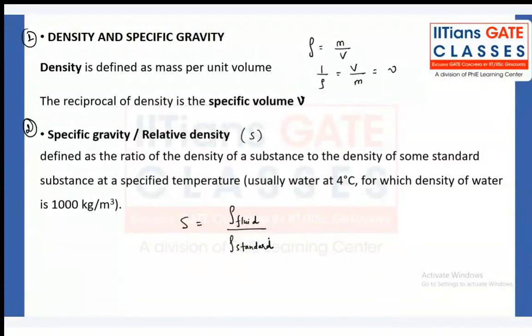Now, which fluid is to be considered as the standard fluid? In case of liquid, we generally consider the density of water at 4 degrees centigrade. In case of gases, we generally consider ideal gas density as the standard fluid. Wherever you want to measure the specific gravity of any gas, the standard reference fluid will be ideal gas. But for liquid, we consider the standard fluid as water.